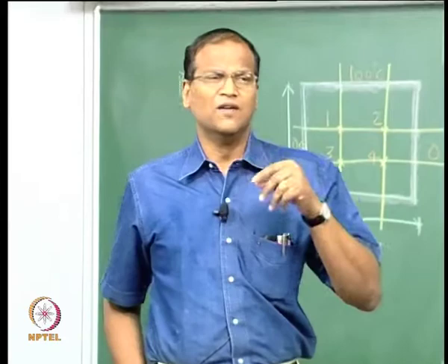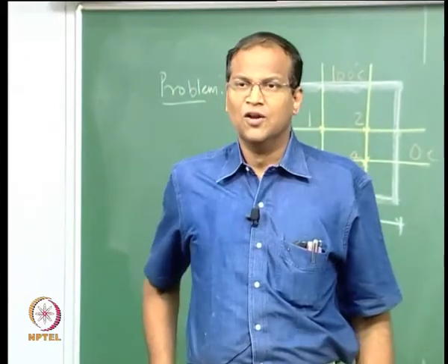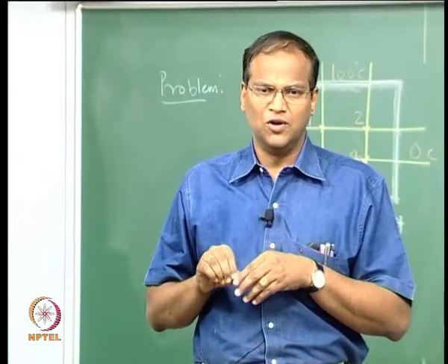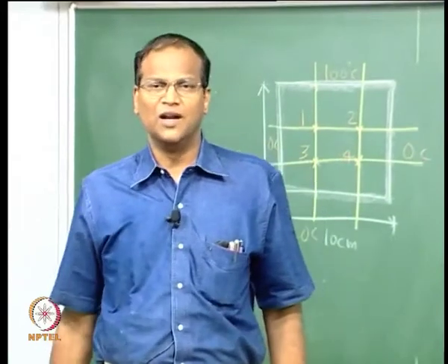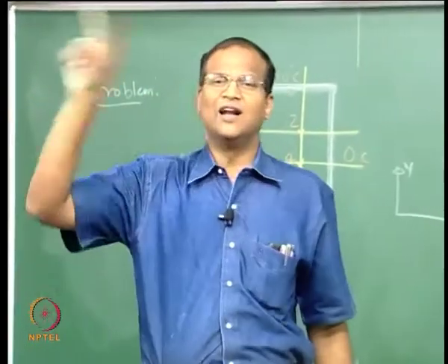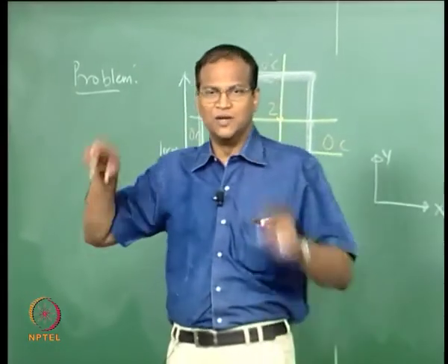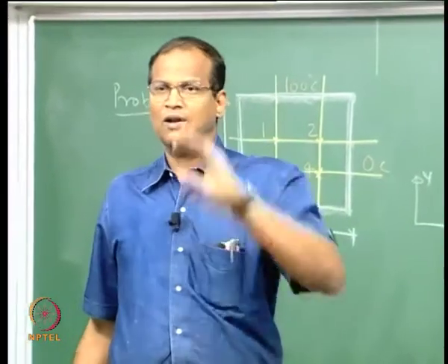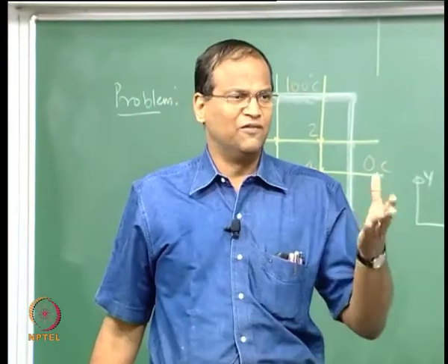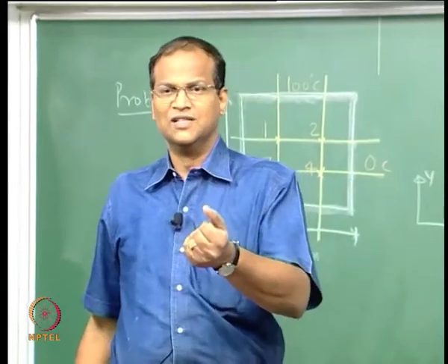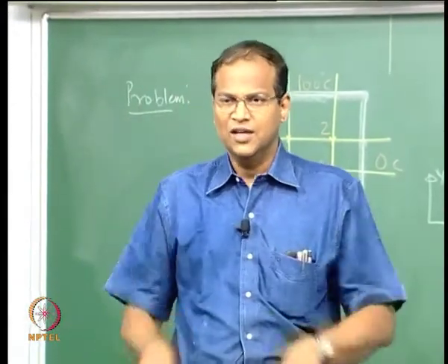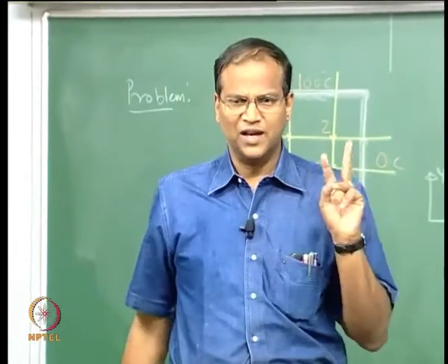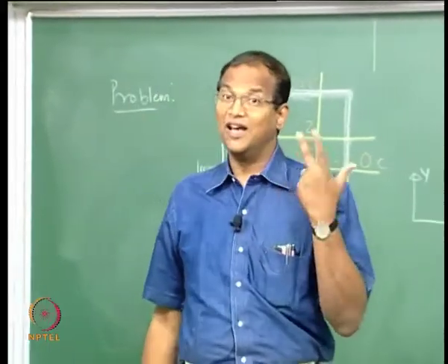You remember in one of the earlier lectures I looked at the Lagrange interpolation scheme. You can use a second order Lagrange polynomial for x and for y, or third order, and get d square T by dx square and d square T by dy square. You will again get Tij as a function of all the neighboring nodes, but here you will not get 25%, 25%, 25%, 25%, depending on your grid. Suppose you first algebraically generate the grid using a cosine function, a tan function, sin theta, cos theta, or a geometric progression. Then for a particular node we can take nodes ahead and behind, or 2 nodes ahead and 2 nodes behind, use a Lagrange interpolation and develop higher order schemes.